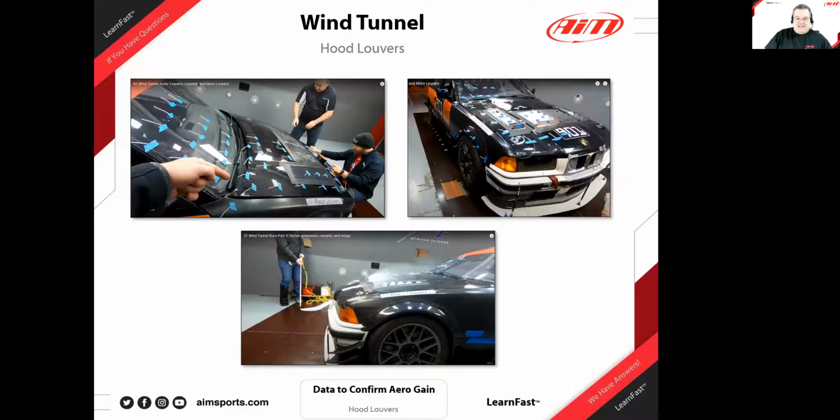From what you just said, it sounds like it's one of those areas where it's the win-win. It's like free, right? Because you're getting downforce without additional drag. Right. There are very few win-wins in aerodynamics, but around the cooling system is one of the best ones you can do. Ducting your radiator on the front side is huge.